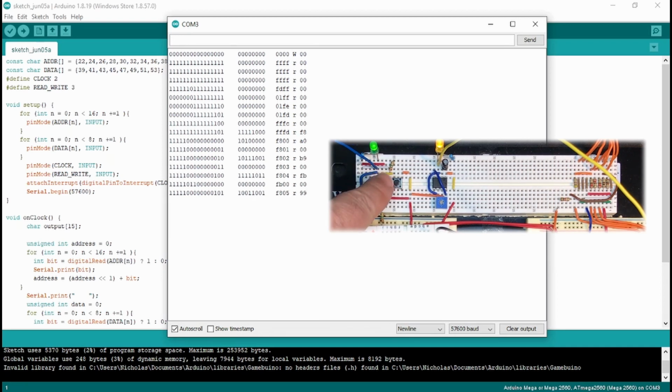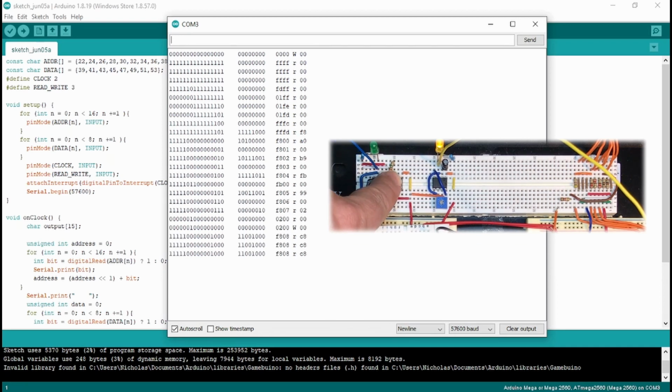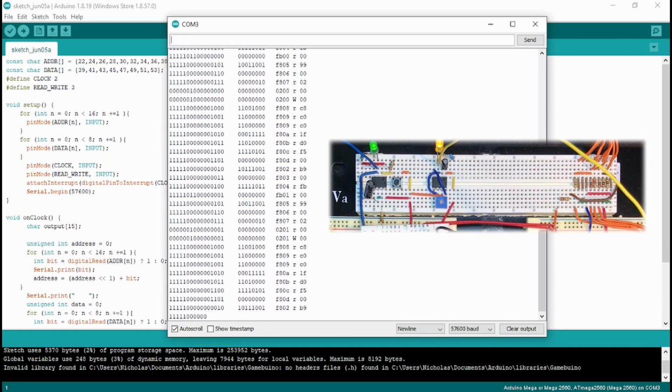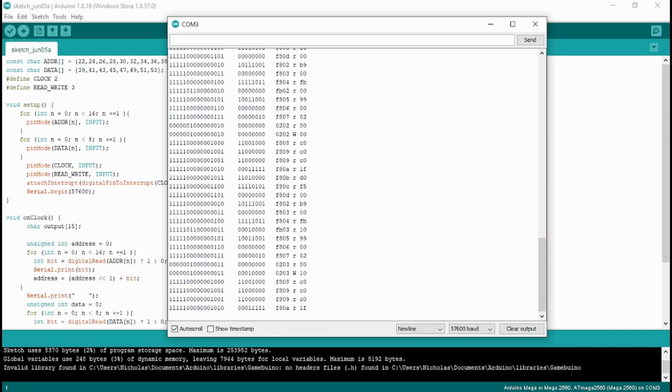Now if I hold down the reset button, you can see that the data output stays the same a little while, and then when I release, it starts to go through the reset sequence of looking at FFFC and FFFD. The program runs by looking at the ROM file at the F800 address for one line of the screen. We'll have a look at the results line by line to see if it's doing what it should right now.